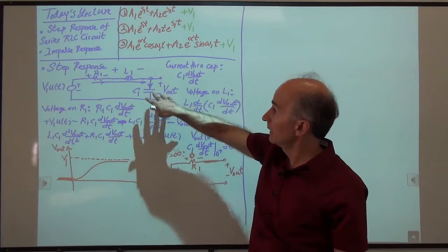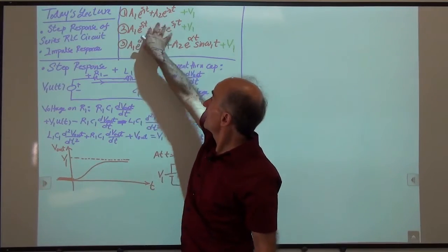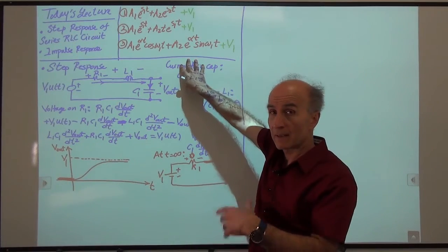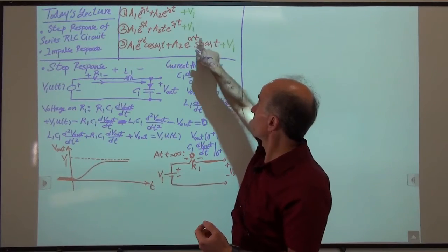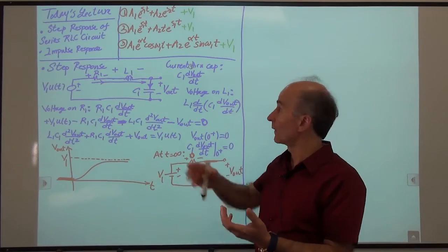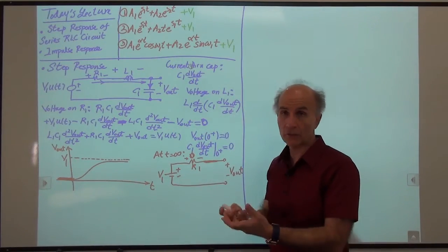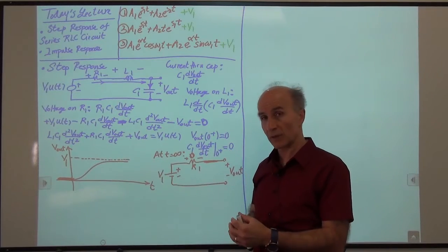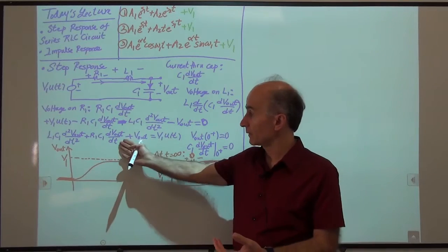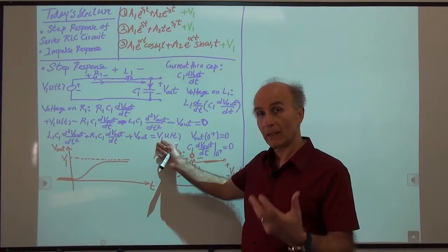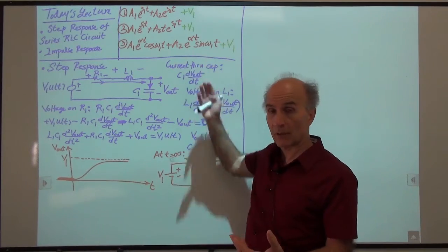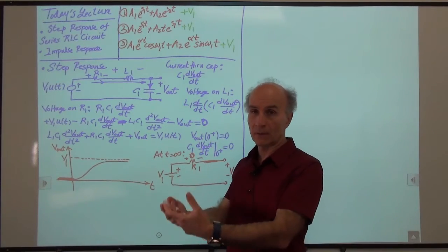We know that in these RLC circuits, all of these exponentials will decay with time, right? They all go to 0. So in all three cases, the final value will be V1 if I just add V1 here. And the rest is just exponential decays with some oscillation or not, and that should satisfy our second order differential equation. So I'm following sort of a heuristic approach. I'm not actually solving this differential equation carefully, but our intuition and our background in differential equations suggest that this is a proper approach to writing the solutions of the system.